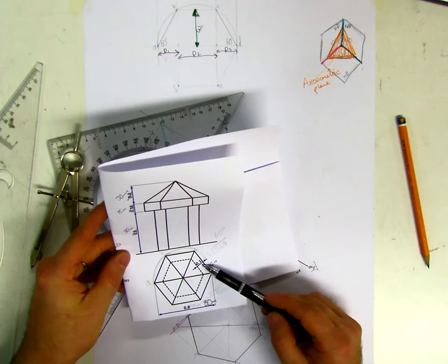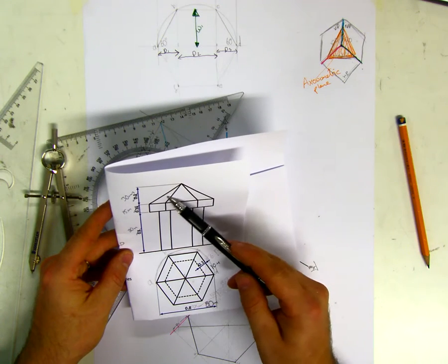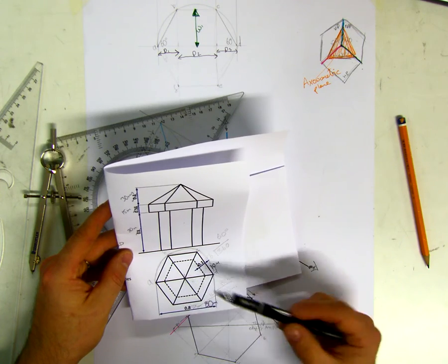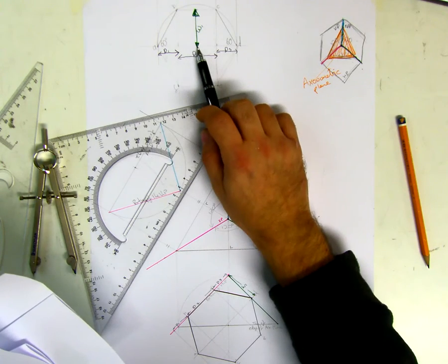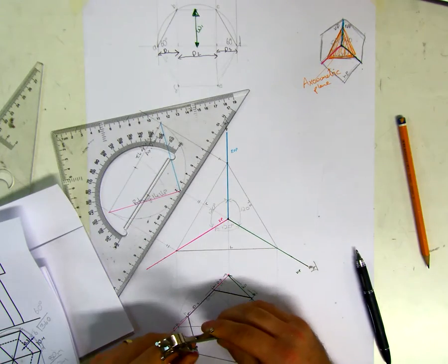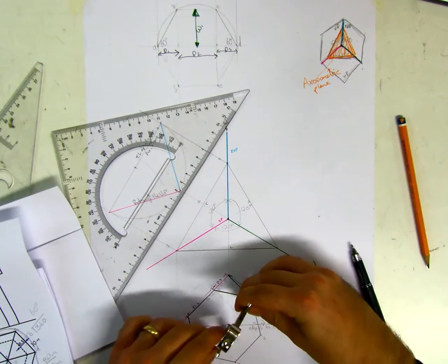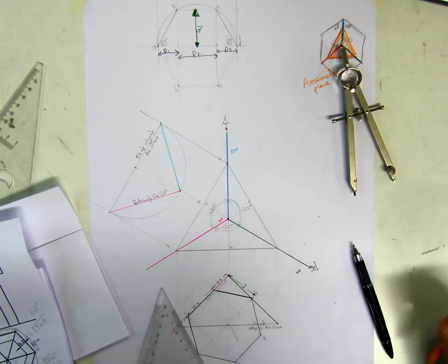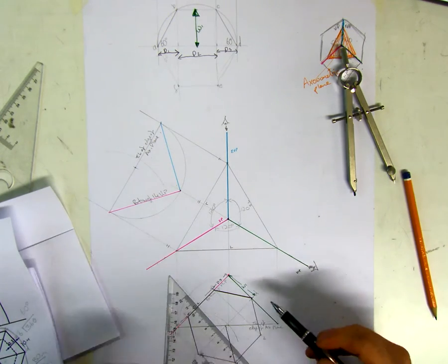So we can see here, if we come in 10 mil parallel to all the edges, will give us the hidden detail of the pillar, and that all the caps here are equilateral triangles, so we need to join them back together once we have the center point. So to find the center point, we have our center line. If we just bisect that, it will give us our center point. So I'm just going to bisect that now. So that's our center point. So all our edges are going to go back to the center point to find our apex.